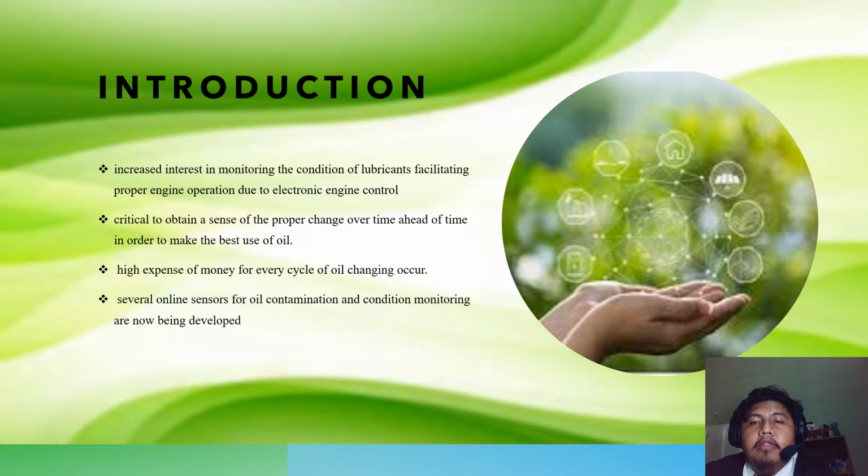Furthermore, it gives a better understanding of the engine's current state, allowing for the detection of a potential engine problem as well as change in lubrication performance due to the use of different engine oils of various qualities. As a result, it's critical to obtain a sense of the proper change time ahead of time in order to make the best use of oil. The current state of the art in oil condition monitoring relies on algorithms aimed at determining the actual oil condition in an indirect manner. This is accomplished by analyzing driving characteristics.